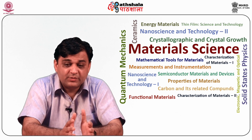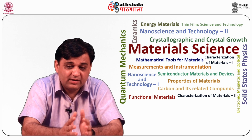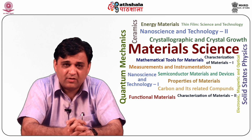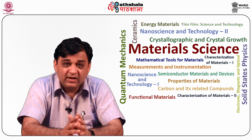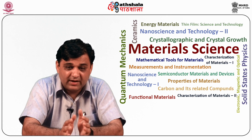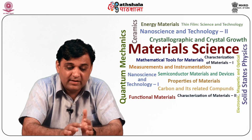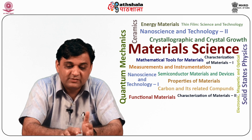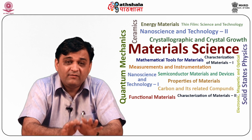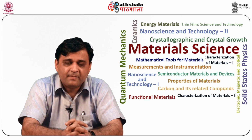So much for the advantages of X-ray reflectivity. Now let me tell you a few disadvantages. It gives only average information on thickness, roughness, and electron density profile. Just like you saw that with AFM and STM you could probe the surface morphology, see the roughness and look at local areas, here we get the average information and not the local information.